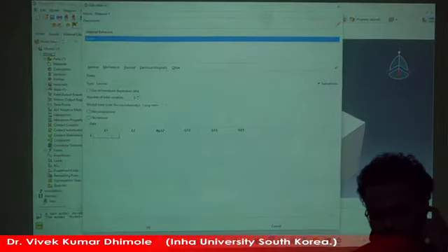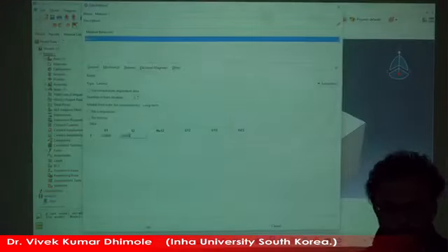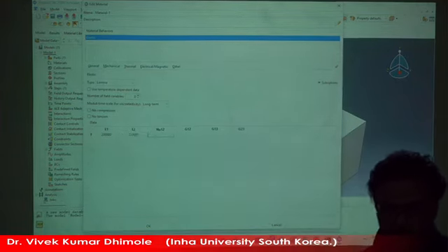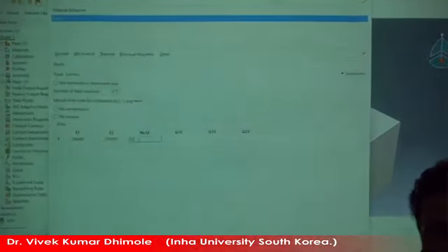So for E1, anything we can take, say 200 gigapascal. No, we are taking megapascal, in mm dimensions. So 200,000 megapascal. Let's say E2 is the same, 200,000. And for the Poisson ratio in the 1-2 direction, let's decide 0.328.